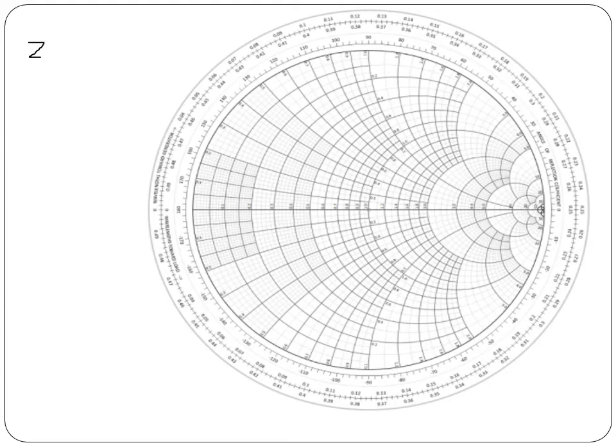ZL is equal to 1 plus j1. We know that the upper half of the diagram represents plus jX. Firstly, note down the R circle, then the X circle.